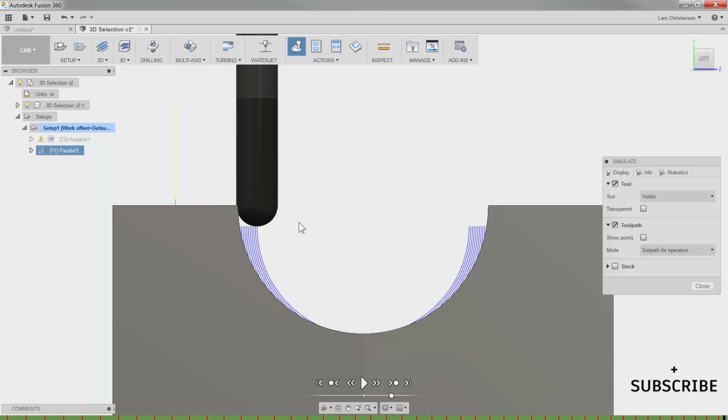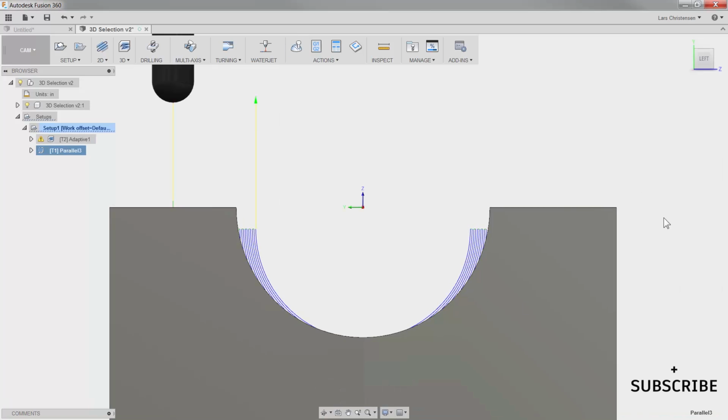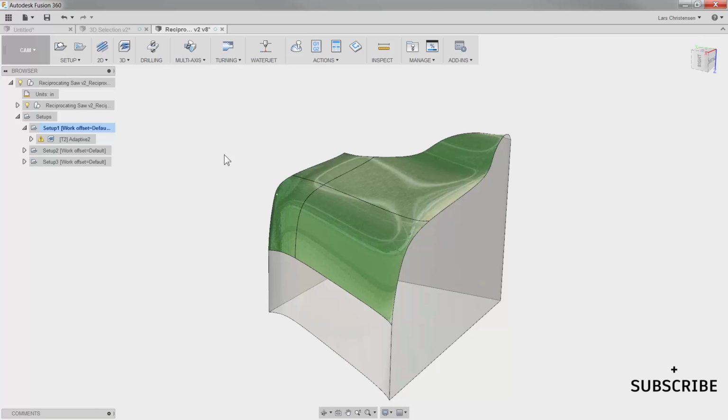With that contact boundary selected, you will actually see that the toolpath finishes right when the ball end mill is letting go of that edge. So just be aware that setting is in there in case you don't really want the center of your end mill to hit that edge. So let's bring up our model from before and go through these settings step by step.